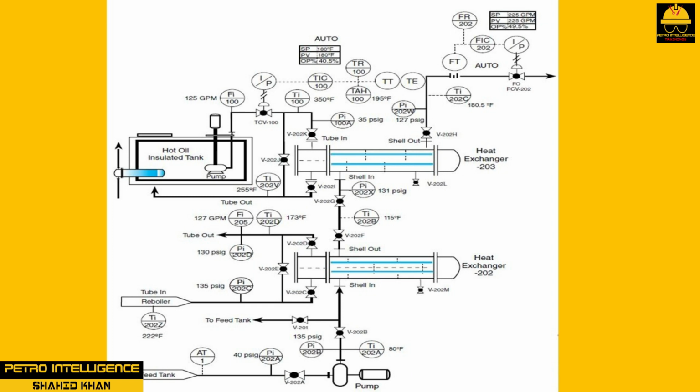During the heat transfer process, the temperature on the reboiler feeds drops from 222 degrees Fahrenheit to 173 degrees Fahrenheit or 105.55 degrees Celsius to 78.33 degrees Celsius. The differential temperature, delta T, is 49 and the difference in the tube inlet pressure at 135 psig and the tube outlet pressure at 130 psig is, delta P, 5. Process technicians carefully monitor these differences over extended run times.